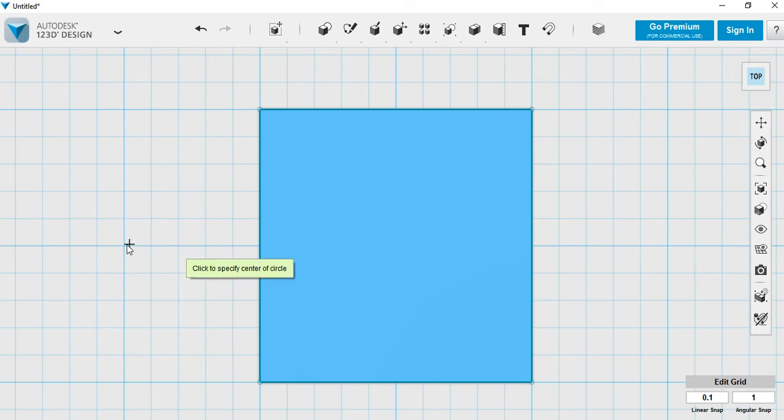Now, the size of the shape you're going to draw depends on the size of the shape on your drawing. You'll only have a front view, and you need to find out the width and the height of the shape you're going to draw. It should be easier on the sheet because you've obviously got squares on the sheet. So you should be able to count the number of squares that correspond to the width of the shape. In my case, it's 4 squares on the grid. Each square is 5 millimeters, so 4 times 5 is 20. So that's 20 millimeters or 2 centimeters.